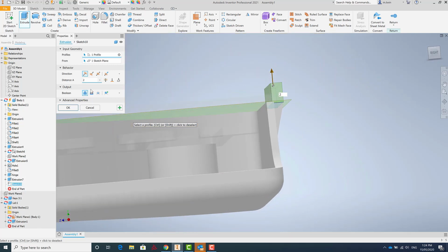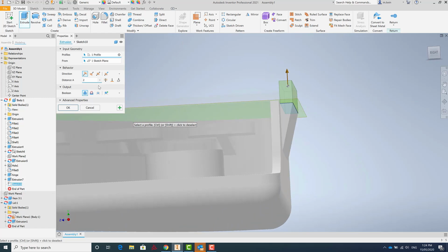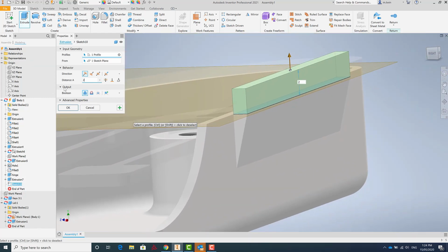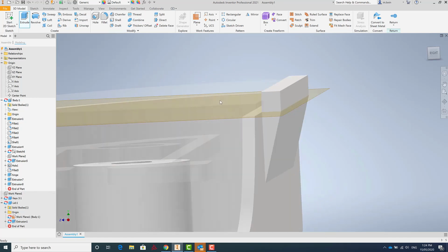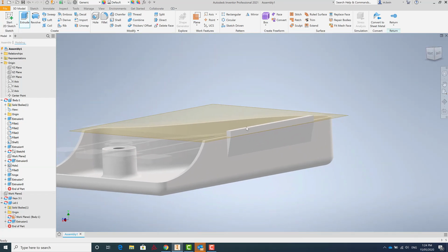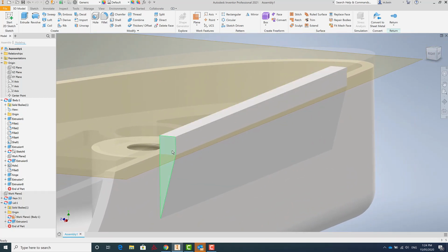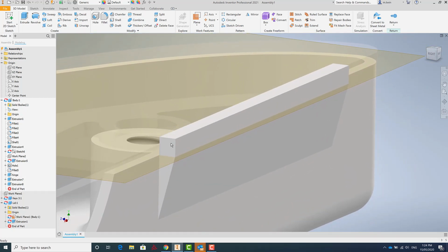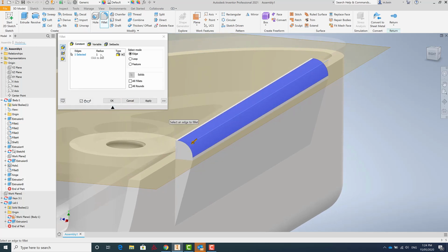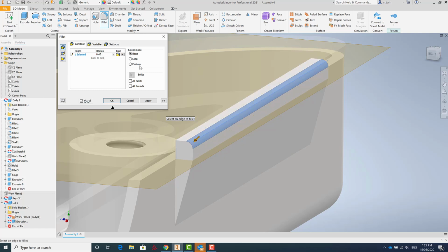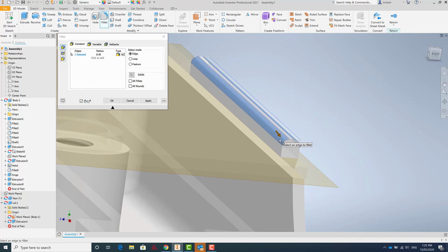How does that fit with our lid? 2 is even probably a little bit too tall. Let's make that 0.2. So we're dealing with really quite precise measurements here, 0.2 of a millimeter. Great. So I've now got what will form the hinge barrel. Now this, I could create another cut profile to round that off, but I'll just use our fillet tool and 1 millimeter is far too big, so we'll make that 0.45 millimeters, just so we've got just a little bit less than the total width.